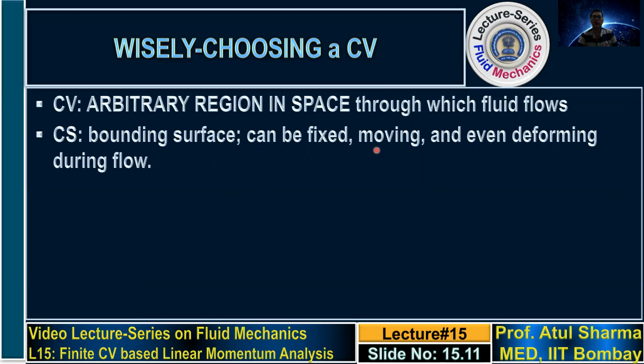Note that Newton's second law, or the momentum analysis that is presented here, corresponds to an inertial flow system, where the control volume that you are taking is either fixed or moving at a constant velocity. You can solve a problem if the aeroplane is moving with a constant velocity and there is an exhaust gas coming out.